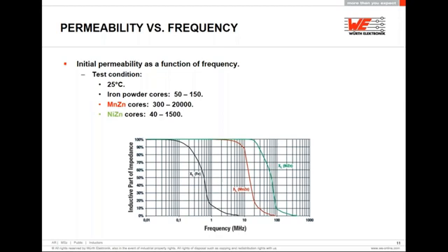Core materials can only be used effectively in the construction of inductors within a limited frequency range, as a result of the frequency-dependent loss components. Core losses rise sharply above a typical frequency limit. The following graph demonstrates the relationship and the limits of these core materials.